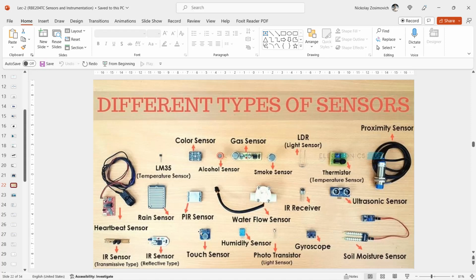So I want to repeat, in this lecture we first introduce a notation system for the quantities used here. To avoid confusion with notation, we define unambiguous symbols for each quantity. For example, in the electrical domain, the symbol epsilon usually stands for dielectric constant, whereas it means strain in the mechanical domain. In this lecture, we use epsilon for dielectric constant only. Strain is denoted by capital S.